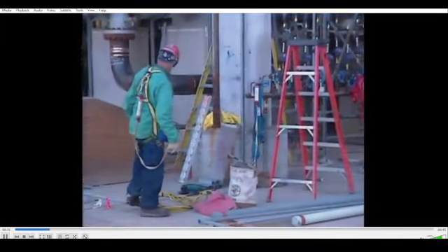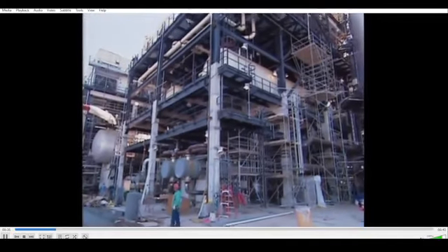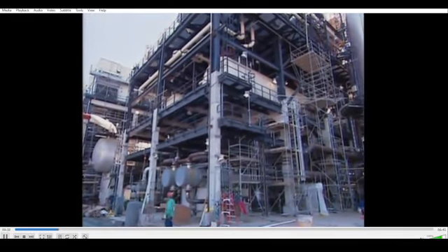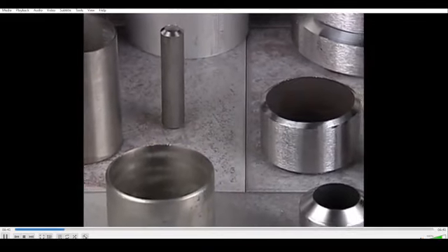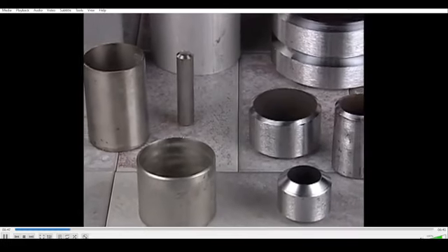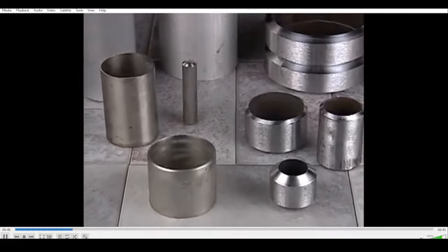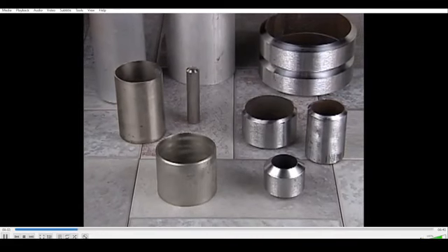facilities. Tubing is also used in these facilities, and although there are differences, the joint designs are similar for pipe and tubing. The type of base metal has an effect on the joint design. For example, steel pipe joints differ from those of aluminum pipe due to thermal conductivity, melting point, and other physical differences. We will confine our discussions here to steel pipe, which makes up the majority of pipe welding.